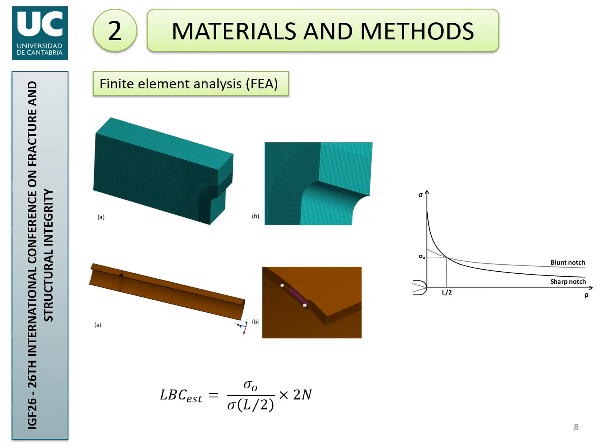So we completed a set of fracture tests on notched fracture mechanics specimens, 3 point bending specimens containing notches, to calibrate L. So we obtained their critical loads, and then we represented the finite element analysis results in terms of the stress fields at the notch tips. And with that, we obtain L and the inherent strength.